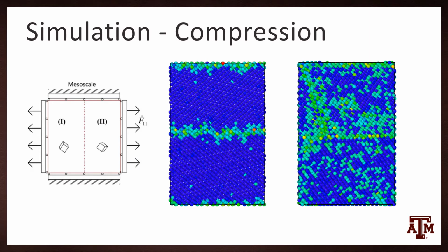The grain in the middle is the same relaxed state shown on a previous slide, with clear defects in the middle and the top and bottom. These are grain boundaries, with those on the top and bottom because the simulation is periodic, so the grains are repeated infinitely in all directions to remove edge effects.